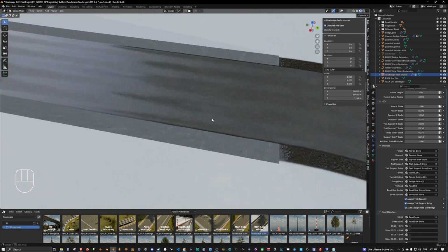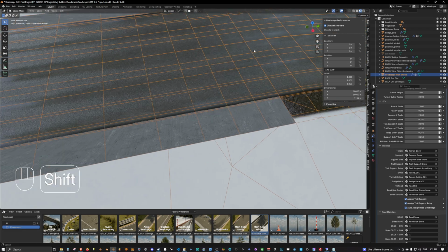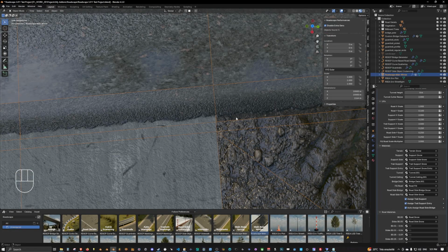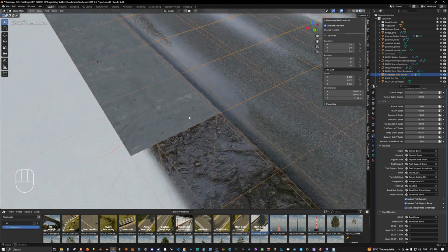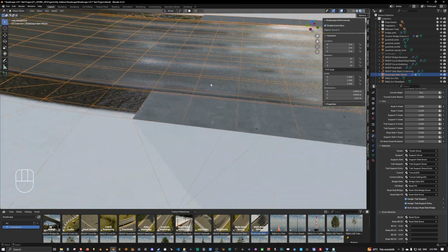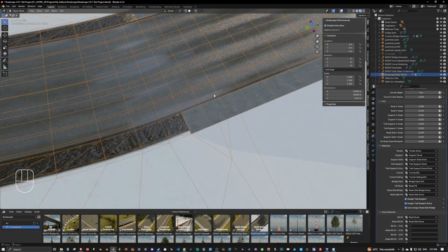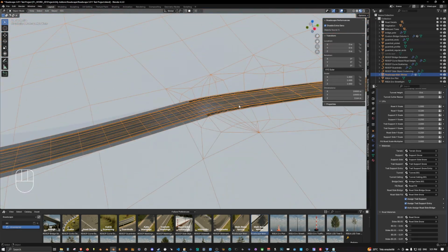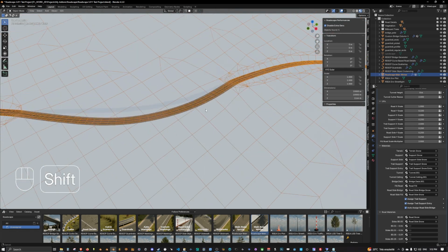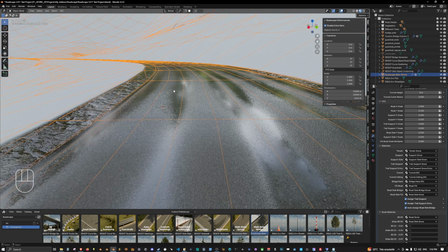By the way, we also have a new feature in Roadscape 3.1, which is the automatic switching of the side road texture from support to road to bridge to road whenever the roadside mesh is above the bridge deck mesh. So this happens automatically and you don't have to change the roadside manually on this part of the bridge and tunnels anymore. Okay. We have the support Z offset feature, which is also here now.